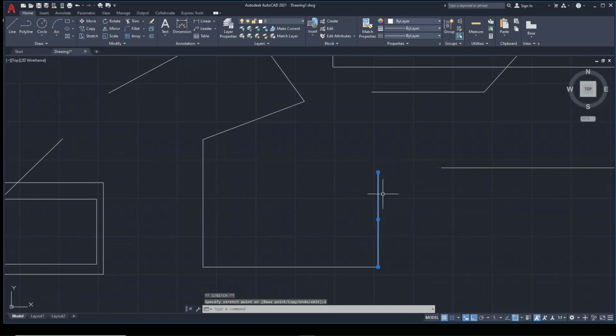And now that line, if I click on it, let's just use the measure tool here. You'll notice that it was 7¼ and I changed that grip to 6¼. So now that line is 6¼. But there are a lot of ways to change the length of a line. You don't have to redraw it in AutoCAD. And we'll talk more about that later.